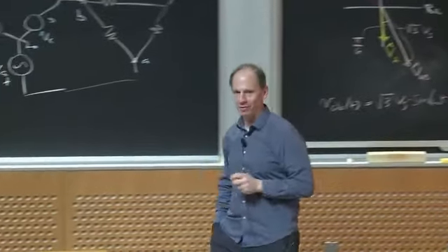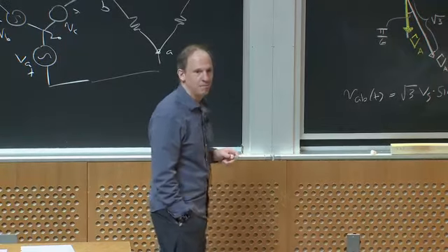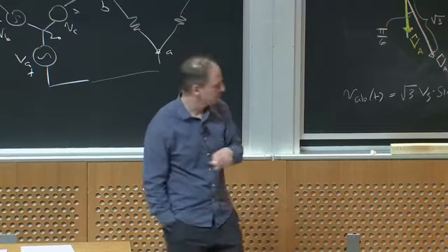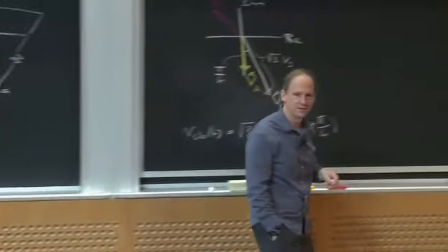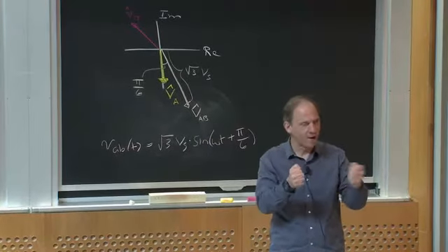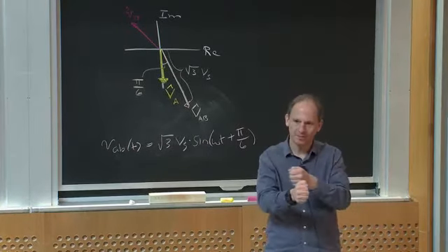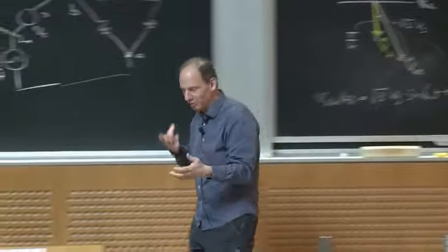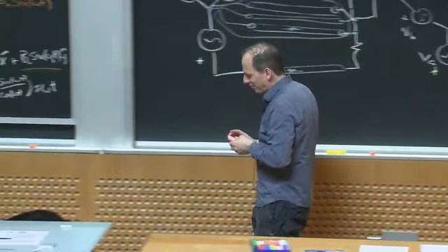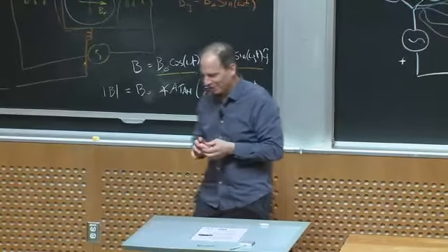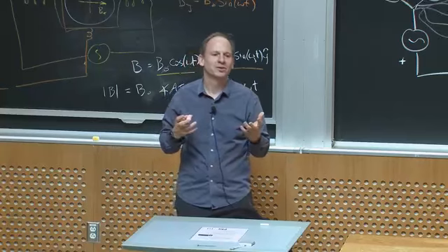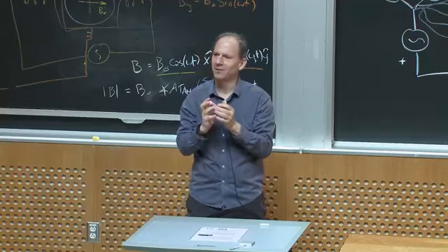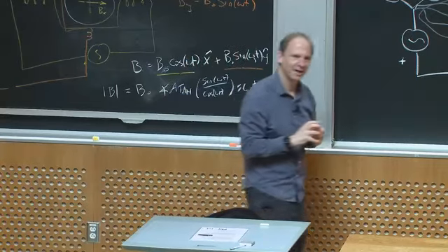The thing that's important about three-phase, however, is making sure which order is which. We'll talk about this, but they often color code the leads. You need to make sure you get your phase order right, because otherwise things rotate in the opposite direction from what you think. There's a famous example where an English researcher made essentially three-phase rail guns using polyphase power to throw a projectile off the end.